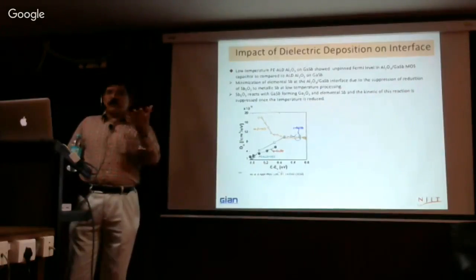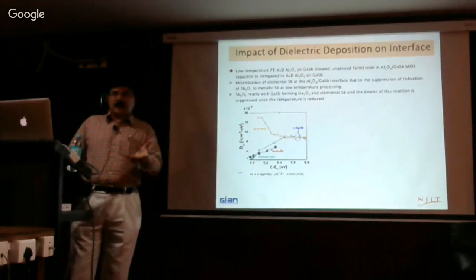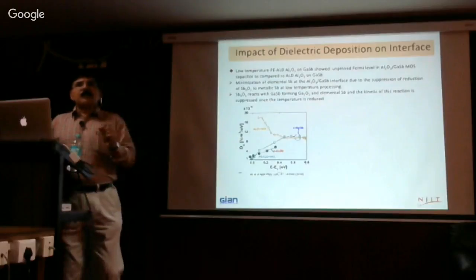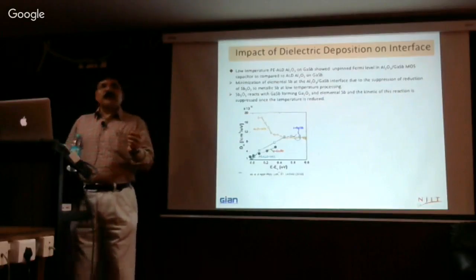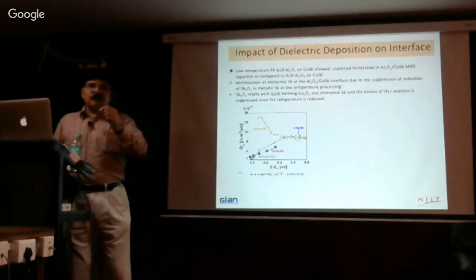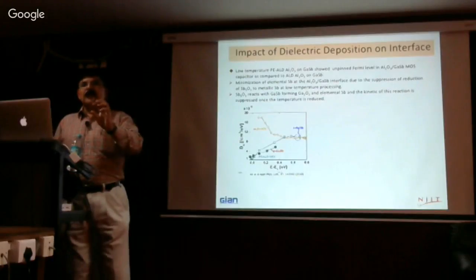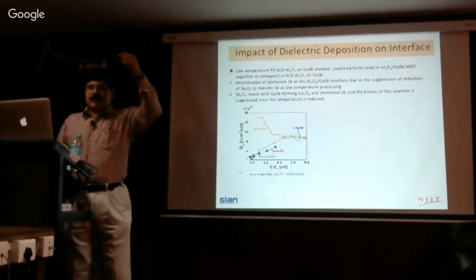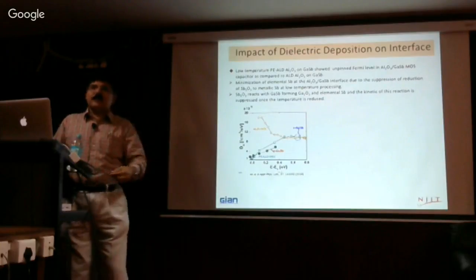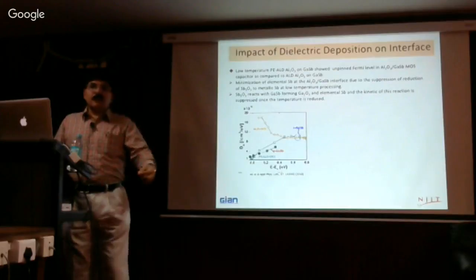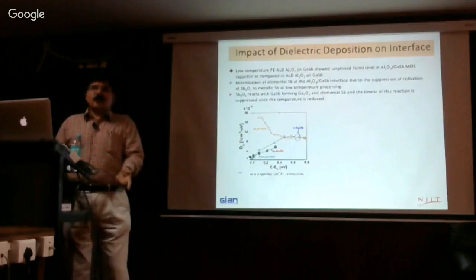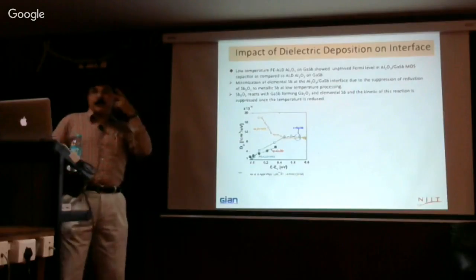In any device, like titanium oxide or anything in solar cells, if the process condition is slightly different, things change. For example, we did some cadmium telluride solar cells. It's very simple. You just put thin films, and then on the top of the contact we put copper. But we annealed it at 200 degrees, and then you can see the copper was sitting all over. It went to the cadmium telluride band gap. It went to the cadmium sulfide band gap. So the device was dead, and that is because of copper. So many things can happen if you change the temperature.